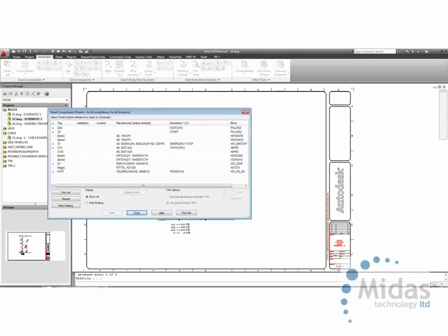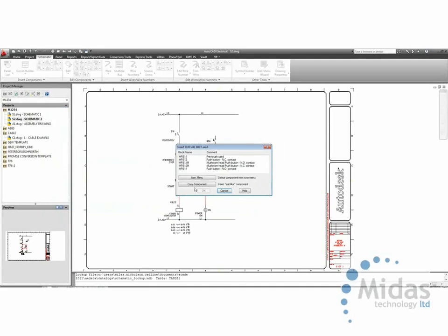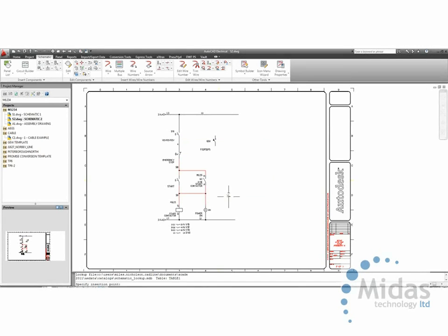And you'll see that S100 is now in our list and it hasn't been placed. Again, I'm going to use panel footprint tag rather than the auto-generated schematic tag, and as I insert it, this will automatically offer me at least PB11 as it did, as I mentioned earlier. As you can see though, it's offering me a few more options, and I'll come round to that in a moment, why it's offering me the additional options. So I'm just going to say OK.